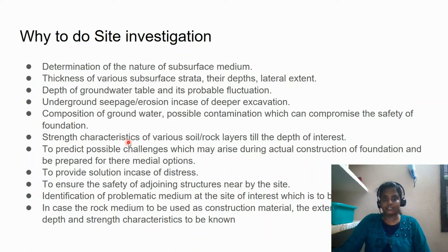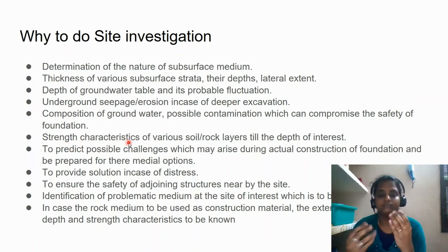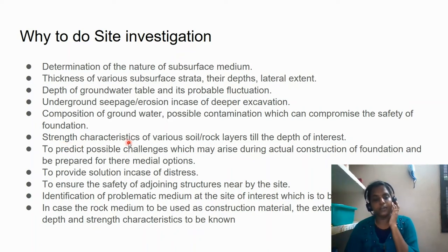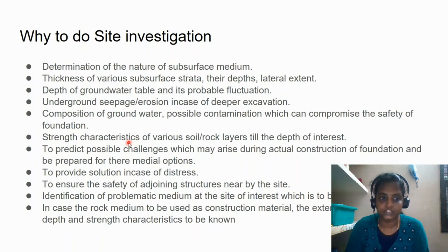Next, the strength characteristics. You have clay or a rock below, and you have to see what the bearing capacity or strength of that layer could be, because once you load it, that soil should not undergo failure. So you have to determine the resistance that layer could offer to your structure.